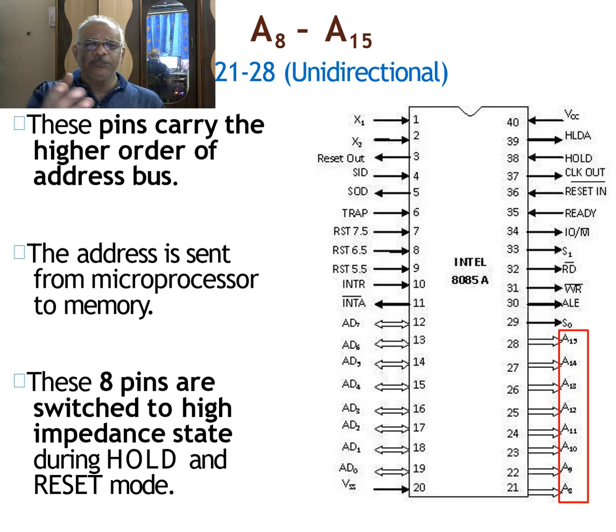Okay, so these pins carry the higher order of the address bus that is written here. I will just read it out. The address is sent from microprocessor to memory, definitely, and the 8 pins are switched to higher impedance state during hold and reset mode. That we will see in due course.